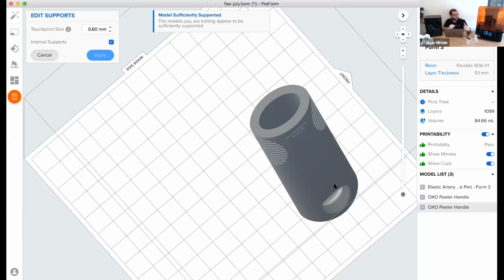If you somehow hacked your Form 3 because you really wanted to compress your material and you told it, hey, slam that build platform really hard into the bottom of the tank, you'd probably dent the tank. You wouldn't tear the film, but it's not good for the life of the tank. So we moved to an approach of changing that first few layers' adherence to entirely rely on different patterns of curing and laser intensity. So those first few layers, the laser intensity, the scan speed, the pattern it scans, is different. And the goal there is to just adhere it through slight over curing, essentially.